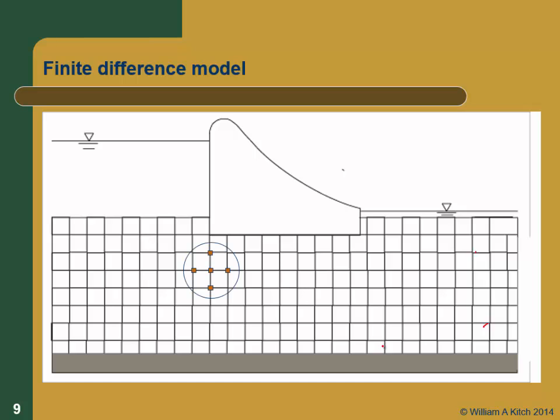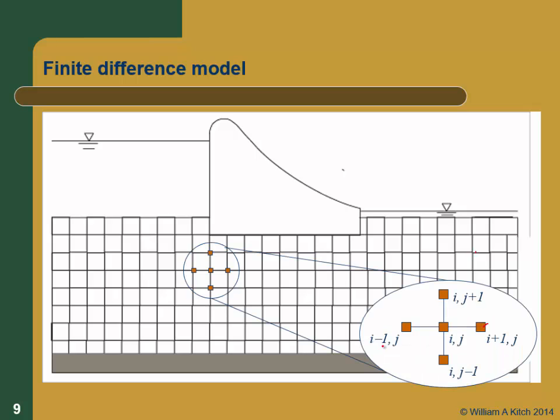And then at every point here, I'm just going to put a node, and all I have to do is pick a value of the head at every point so that it's equal to the average of the other ones. But I'm missing what part of my differential equation solution right now? To give you a big hint, that's the general solution. What have I not accounted for so far? No, well, I'm assuming k is equal. The two k's are equal. I can do this with the alpha in there, right?